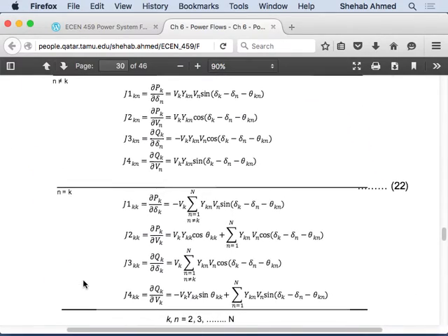So that's what PowerWorld does. And I will show you a slide where PowerWorld constructs the Jacobian matrix every iteration. So you can actually make PowerWorld step through, do one iteration and stop. You can use this as a way to check your answers. If you want to build a small system and, for example, do 2 iterations to confirm, you can make PowerWorld do one iteration and stop. I think I have one slide here that shows how to do that.